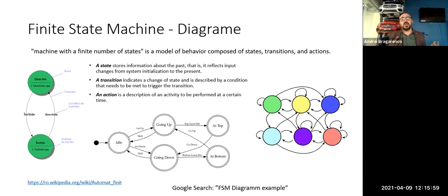Let's say that depending on the state, we are going to control by specific parameters for PID control, and on another state we are going to provide other parameters, and by changing the states we provide different actions. Now we just have to define how we transfer from one state to another.